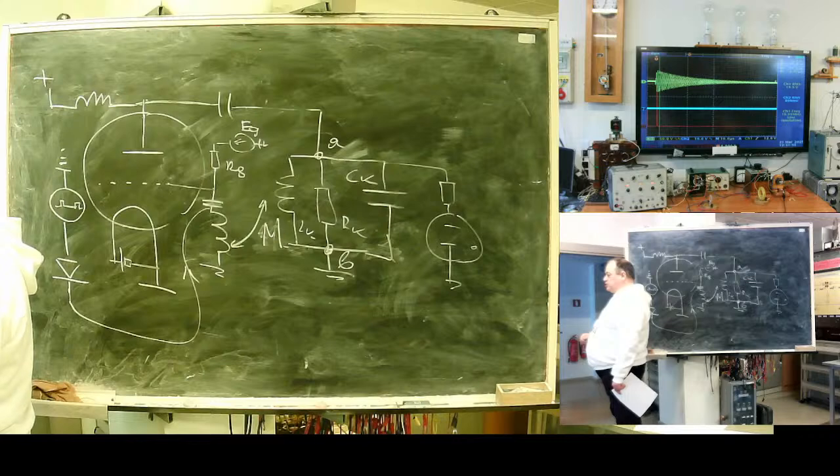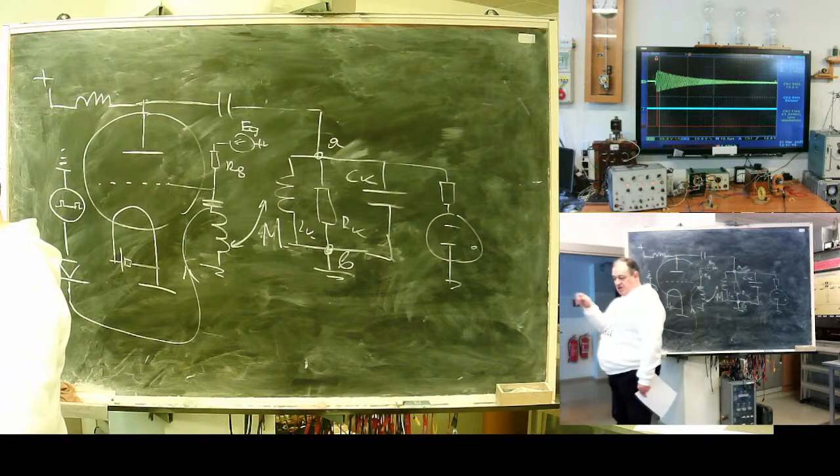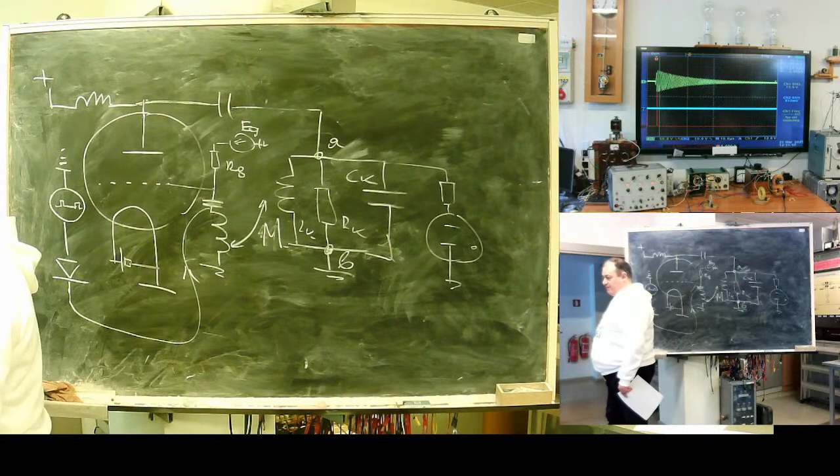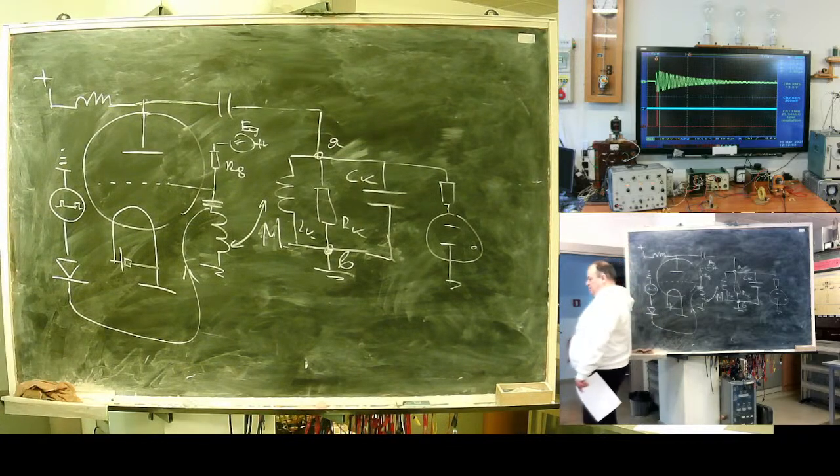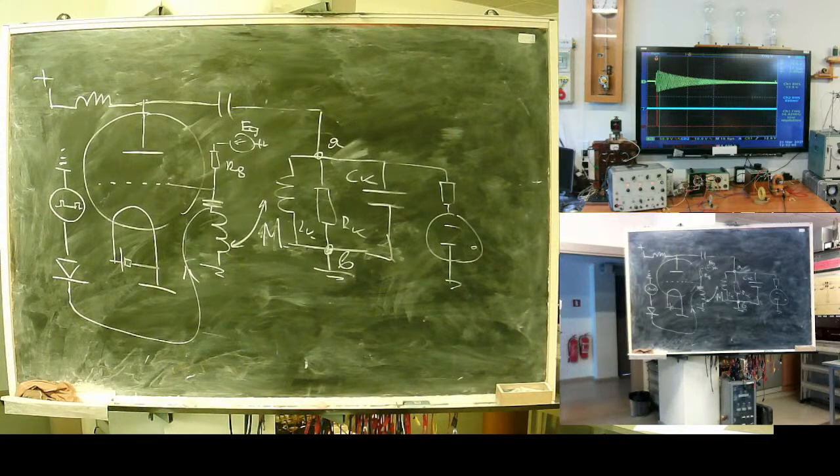At low voltage it does nothing. When the voltage is high enough, gas discharge appears, and it will take energy from the resonance circuit, then transfer it to the heated line. It's a limiter.